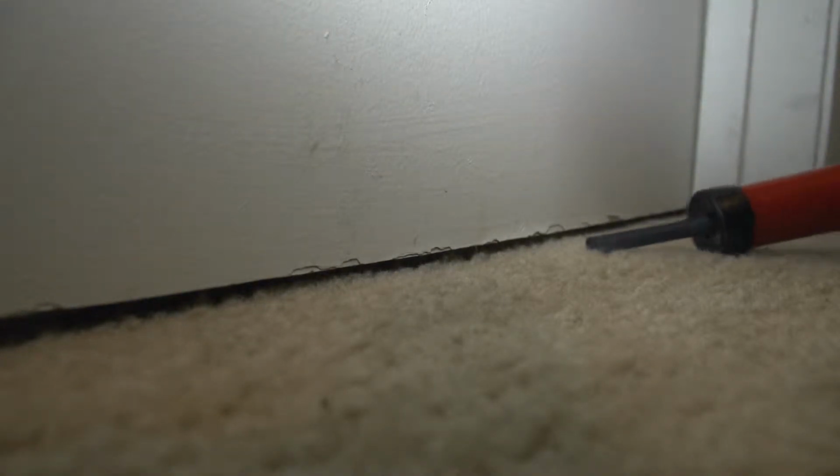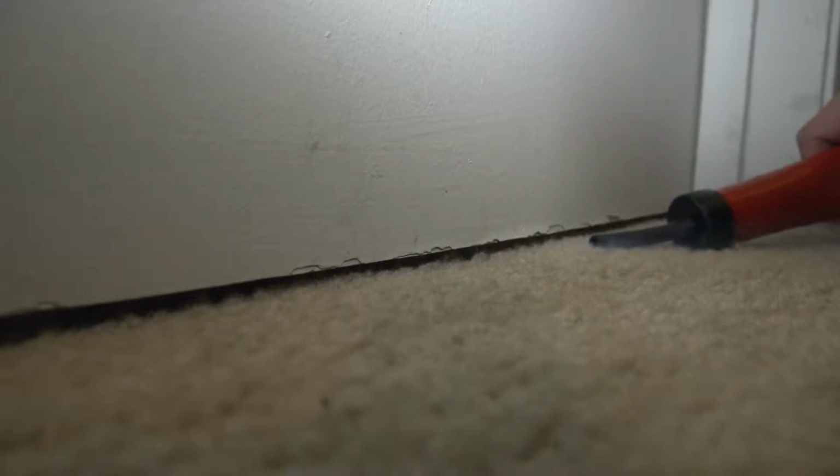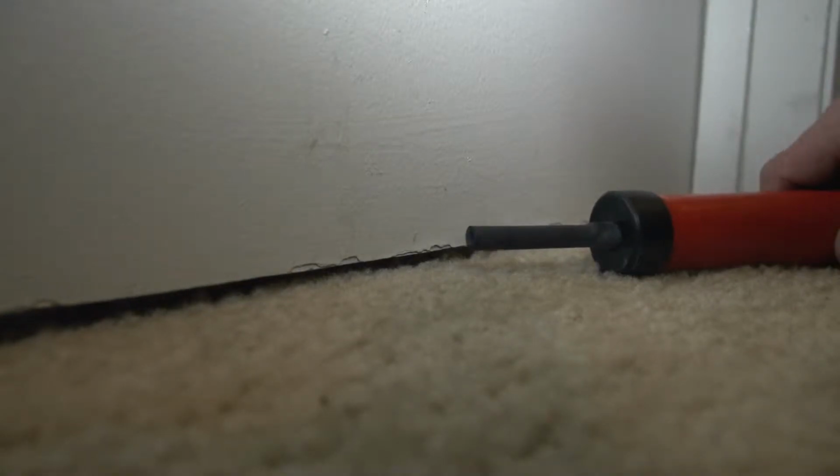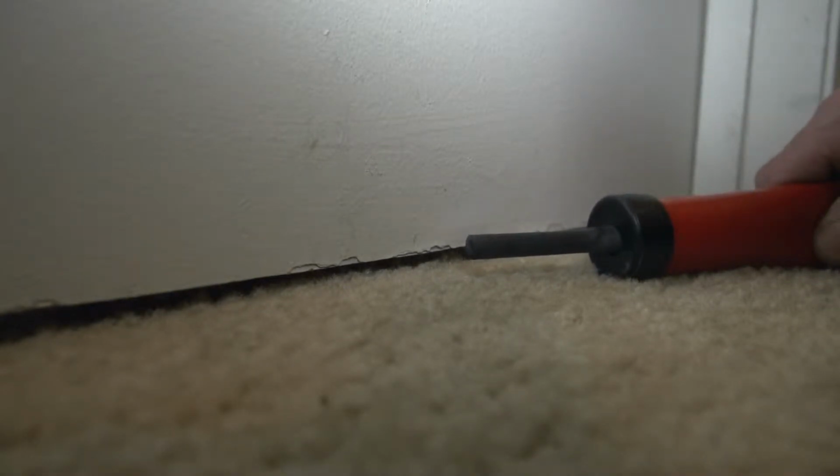As we go around the house and open and close doors, there's another simple method that we can use to determine if these doors should be opened or closed. And that's to use a smoke stick. So we're going to go around to our interior doors now, and we're going to partially close them and puff a little smoke in the direction of the crack that's left in the open door. If that smoke blows towards your nose, you should leave the door closed.